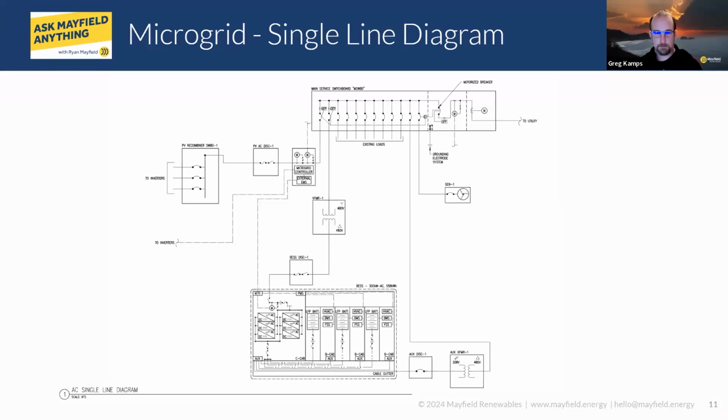Yeah. So, as we're looking at this, there are multiple ways to go about it. In this case, we're using motorized breakers and a microgrid controller to do that isolation from the grid or connection to the grid, as the case may be. Sometimes we'll actually see contactors. Sometimes if it's a small enough system, the microgrid interconnect device might be integrated with the power electronics. So this is just one of probably lots of ways that we can do this. Just wanted to show that to folks.